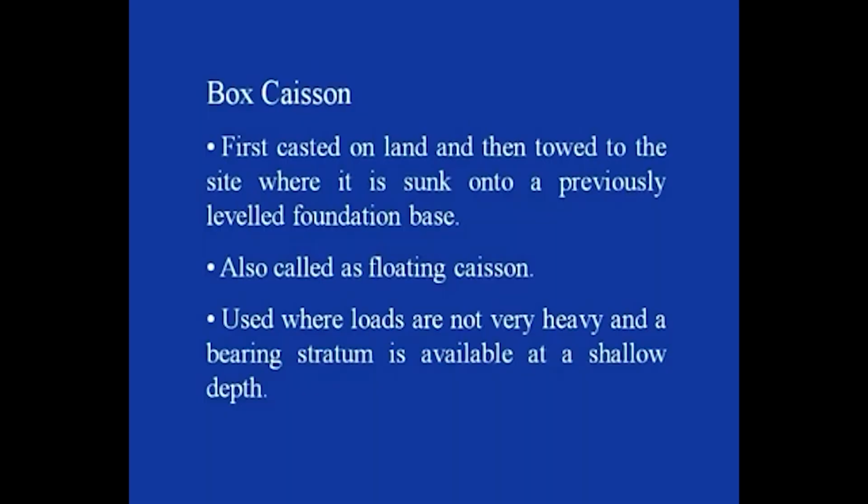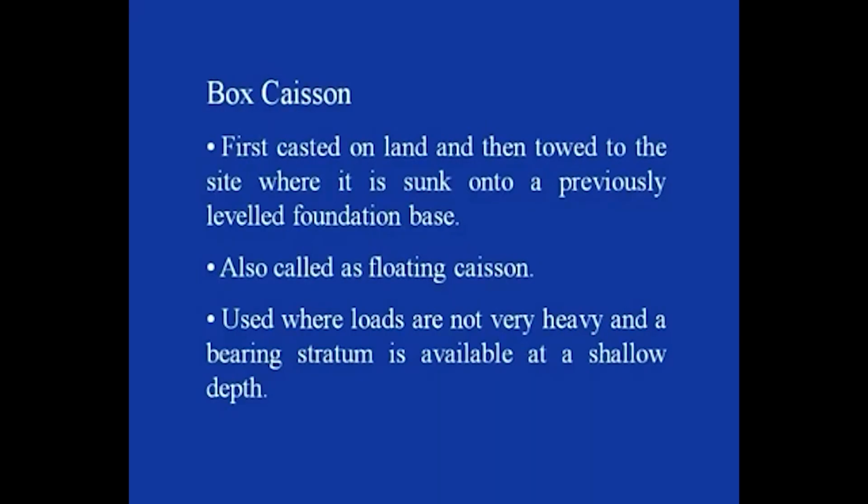Some of the features of this type of caisson is that it is first casted on land and then towed to the site where it is sunk onto the previously leveled foundation base. So the prerequisite for the construction of this type of well is that you have to have a pre-leveled foundation base before you start sinking the well, and this is to be first casted on the land and then it is transported to the site where it is to be sunk, and therefore this is also called a floating caisson,